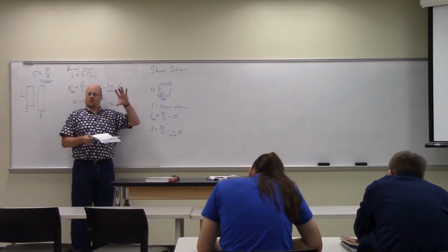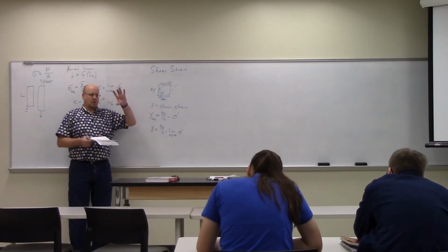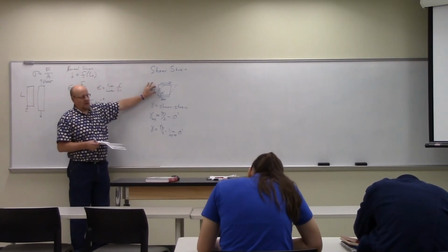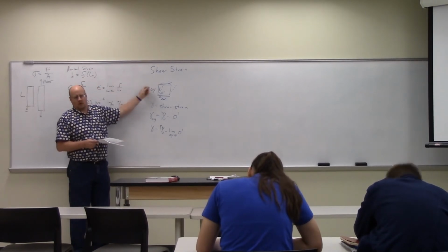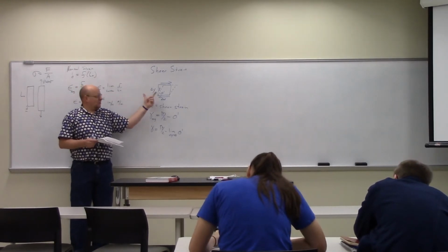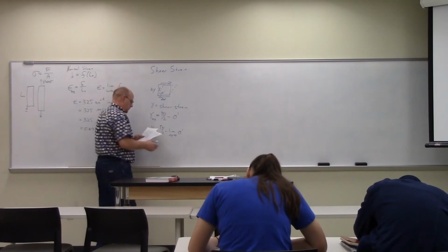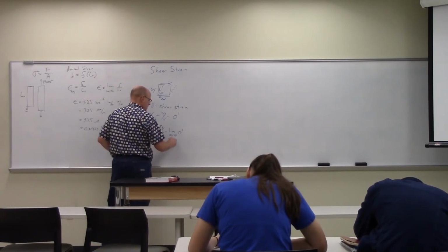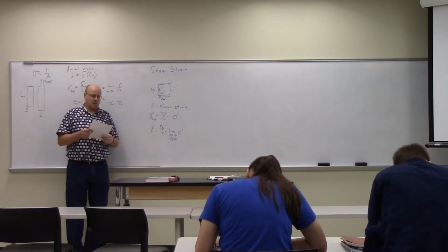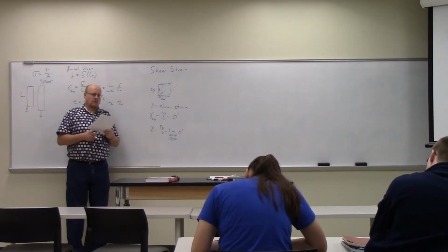In other words, I have a chunk that has a shear strain on it. I want to find the local shear strain at a point. I have to take that chunk and shrink it down and see how small it gets. Actually, technically delta x would also be going to 0. You want to shrink this chunk down to a point. Does that make sense?